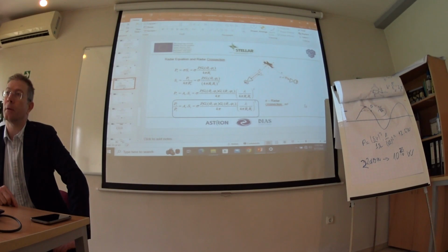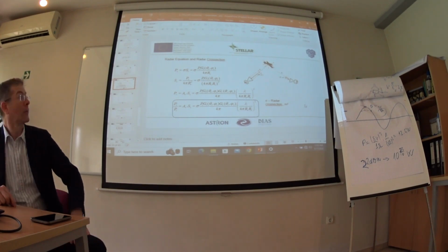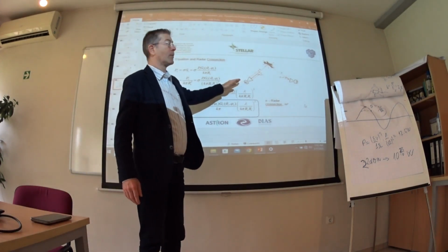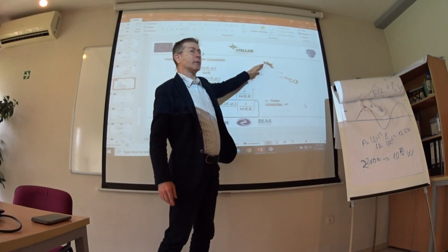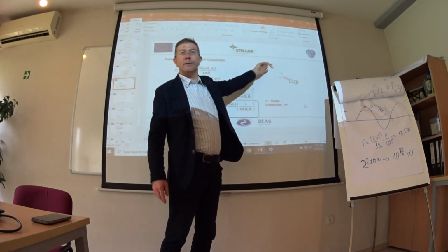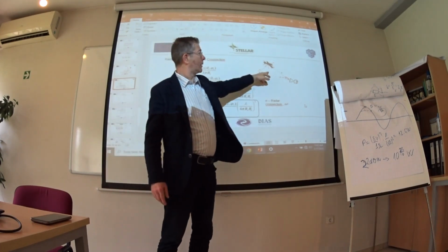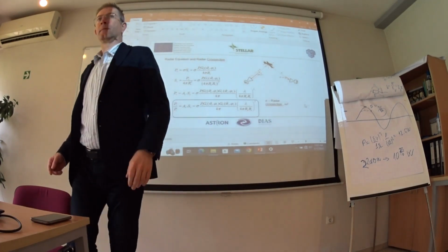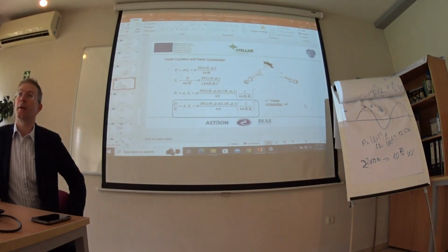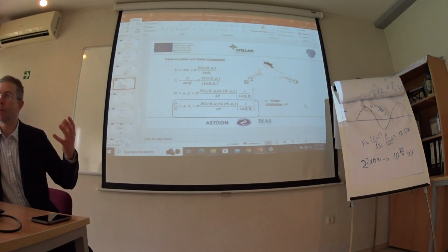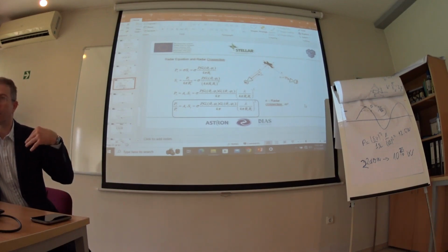Radar equation and radar cross section. What does that mean? It means we transmit a signal, it hits the target, gets reflected back, and gets received by the radar antenna. The receive antenna could be the same as the transmit antenna, or could be a different antenna. So this is called monostatic scenario, bistatic scenario.